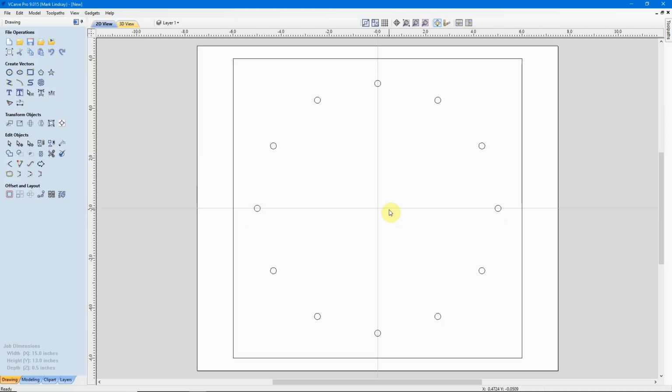The easiest way to do this in this case is, yes, I could go to each one individually and increase their size. But I'll just go ahead and select these three by selecting the first one, hold down Shift, select this one, and tap Delete on my keyboard. That leaves me with this one here, which I can then resize, then create a circular array of 4 dots.